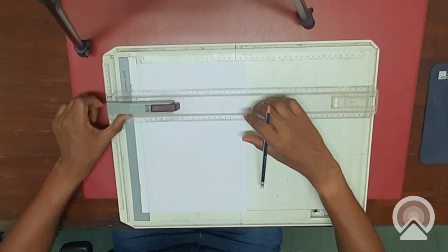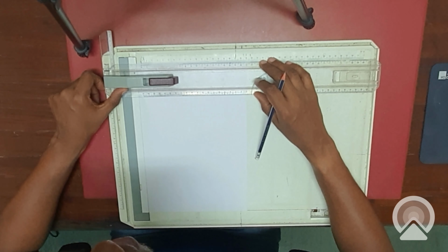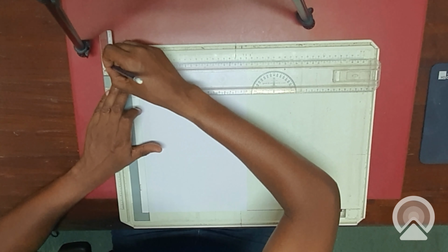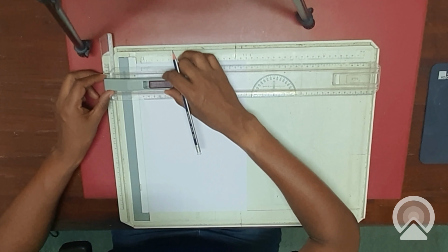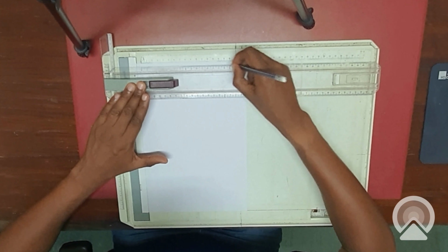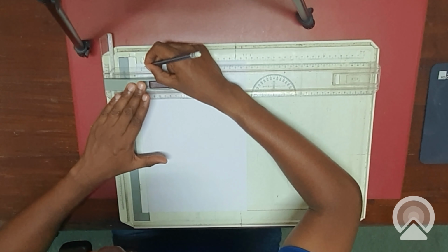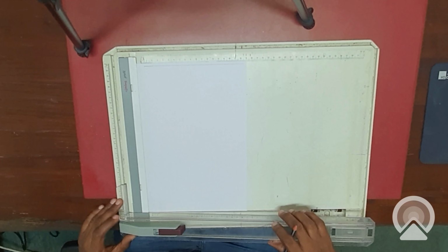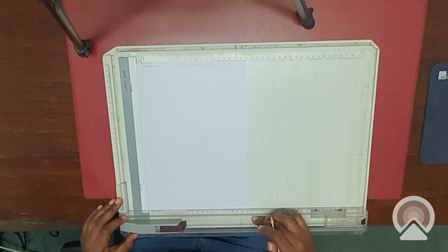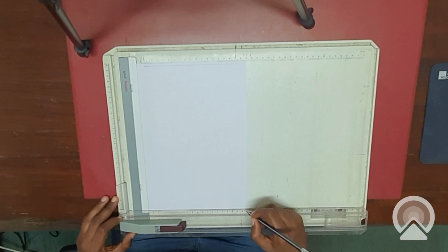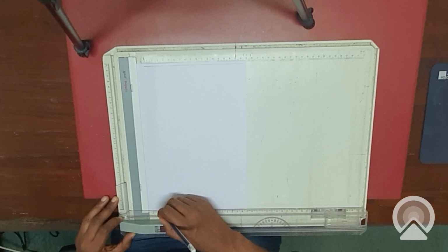Now you can use your horizontal ruler to measure. If you can see here, at the top of this one is where the dimension ends. Measure, counting 5 millimeters, you get somewhere here. Now you can draw your horizontal line for the top margin starting from 185 to 5 millimeters. That is, you are ensuring you get 25 here and then 5 here. You can do the same for the lower part, but the beauty of the lower part is that when you put your mark on 0, the space below is equal to 5 millimeters. So you just draw from 185 to 5.